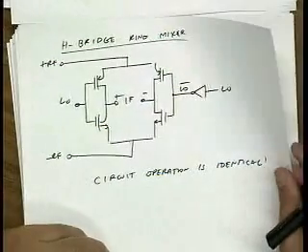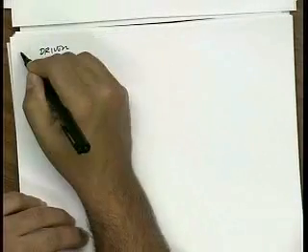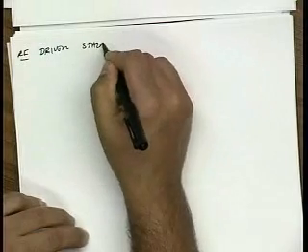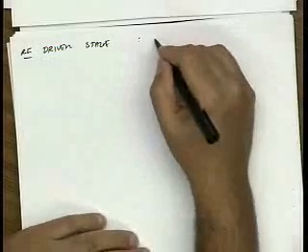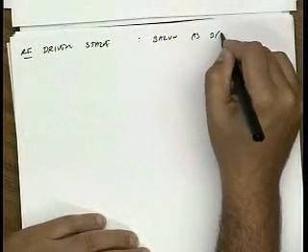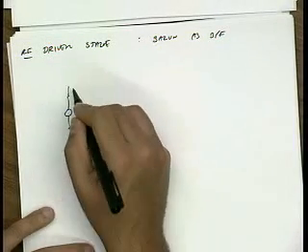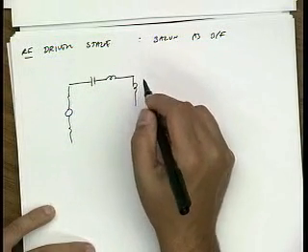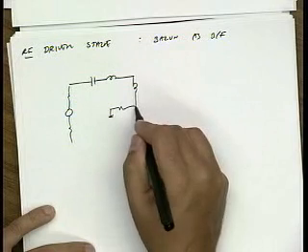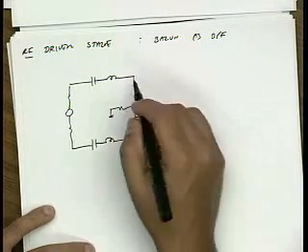Let me show you some ways that you could also drive this circuit. We've been drawing some driver stage. Let's call it the RF driver stage. You know, we've been drawing these floating RF stages. One is to use a balun. Another one is we could use basically a matching network to try to maximize the voltage swing at the RF port.